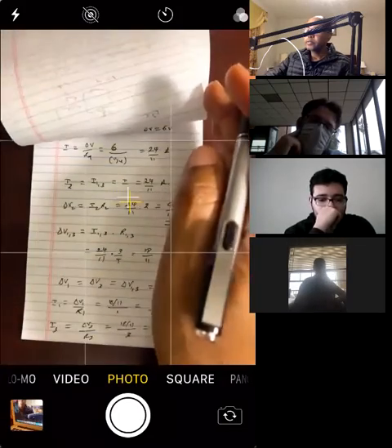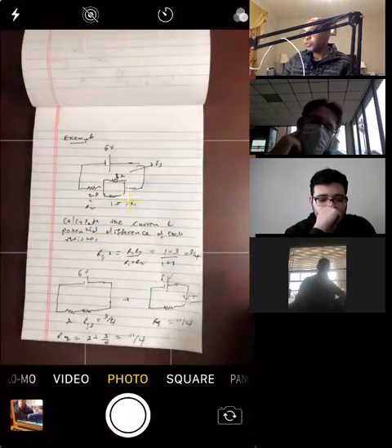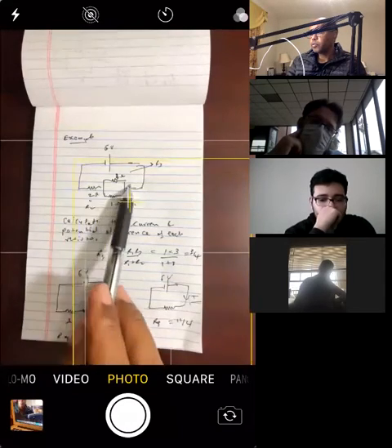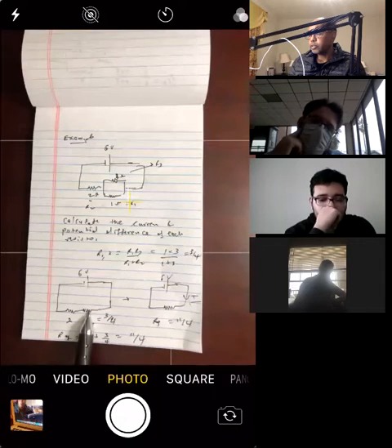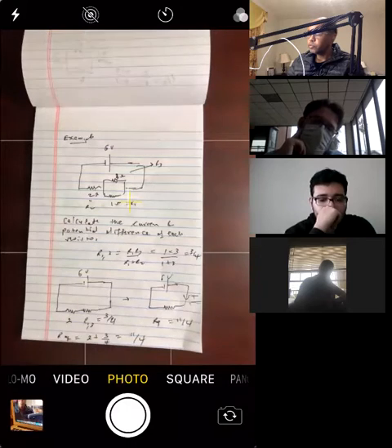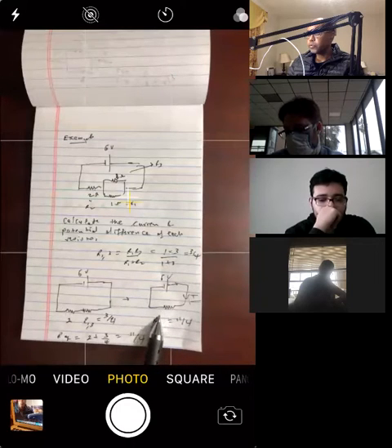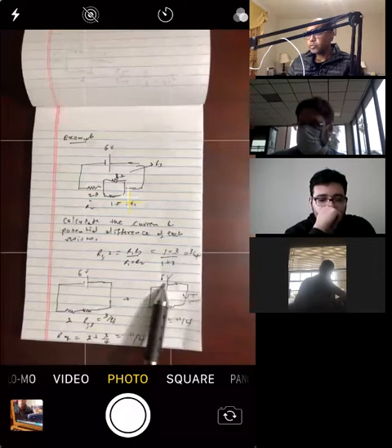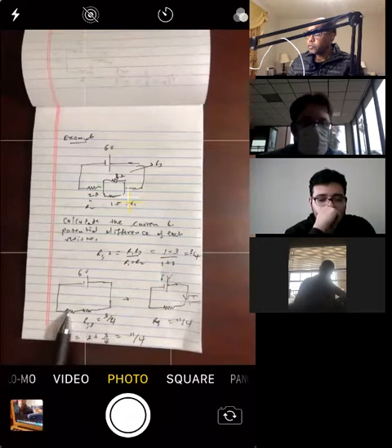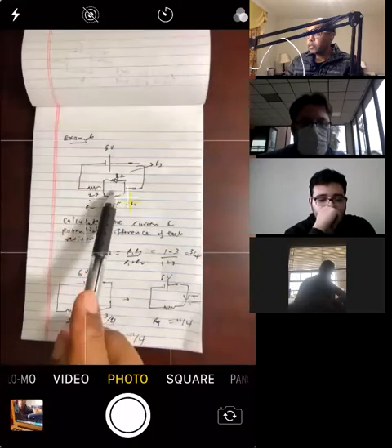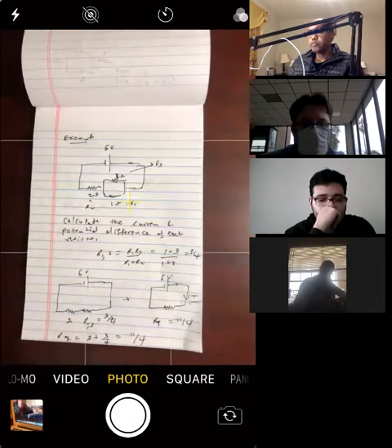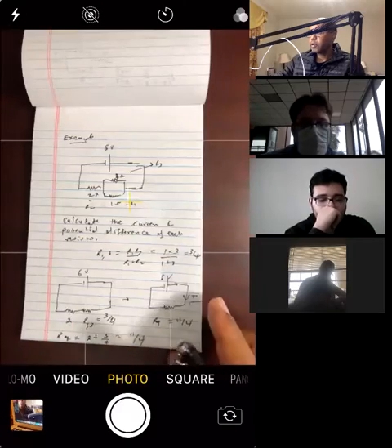We got the currents and the potential differences for each resistor. So the main thing is first you should simplify. These two are parallel. You combine them together, we get this combination. So you've got a series combination of these two and this, which is parallel combination of these two. And then we further simplify. We find the equivalent of these two, and then we finally get a circuit with one resistor. Okay. So from that, you can calculate the current from this circuit. When you go back, these two, so they're in series, they're going to have the same current, okay? So you have the current for this one, the current for this one. You calculate the potential difference for this one, and then you go back, since these are connected in parallel, they're going to have the same potential difference, okay? So that way you can solve for everything, all right?